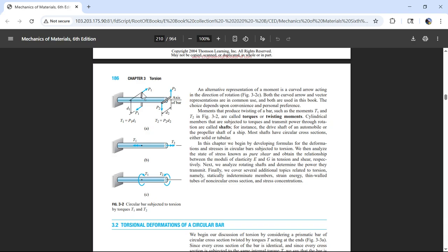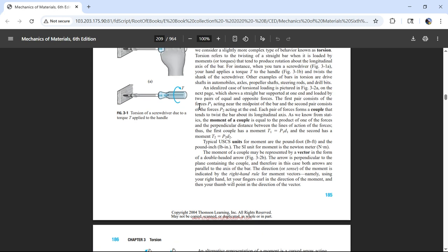Let's say this is up at a 45. Well, let's not get into that, because if this was up at a 45, you'd have an upward force, and something would have to apply a force down for it to be in equilibrium. But hell yeah. So parallel forces, shortest distance between them, perpendicular, kind of the definition of the moment generated by a couple.